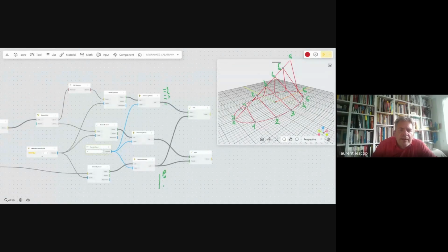And when you use line, they connect 1 with 1, 2 with 2, 3 with 3, 4 with 4. Okay, and the error that we had is because 0 is connected to 0, which is good, but it creates a one-point line, and so the system doesn't accept it. It says no, you can't have a one-point line.